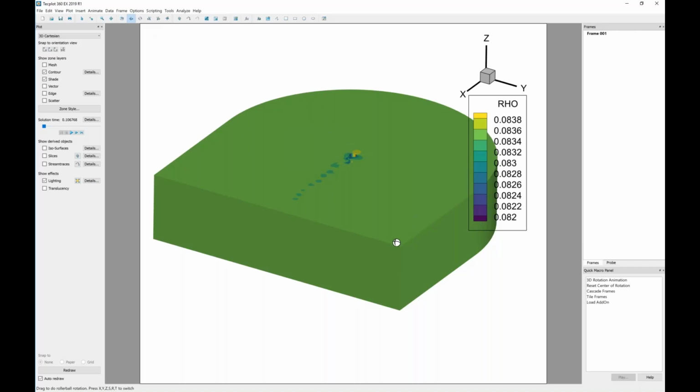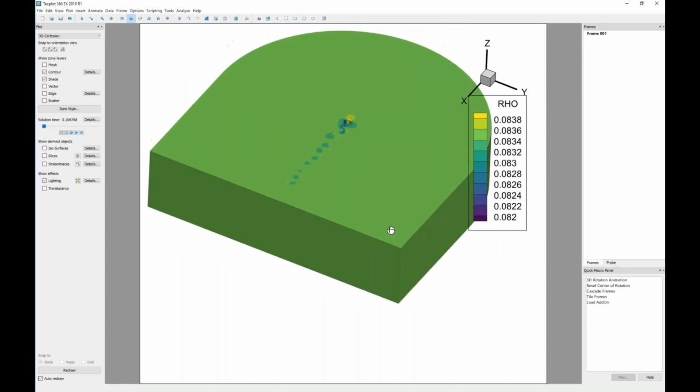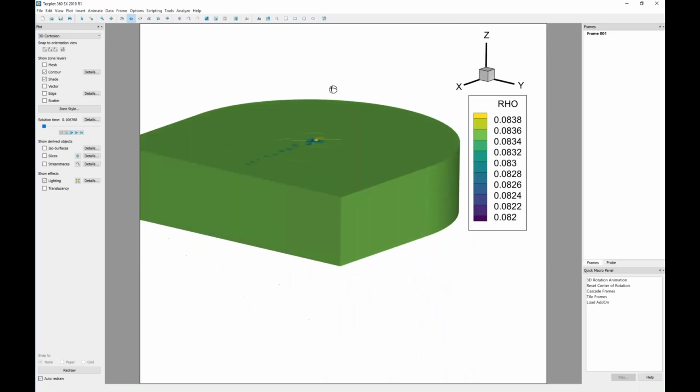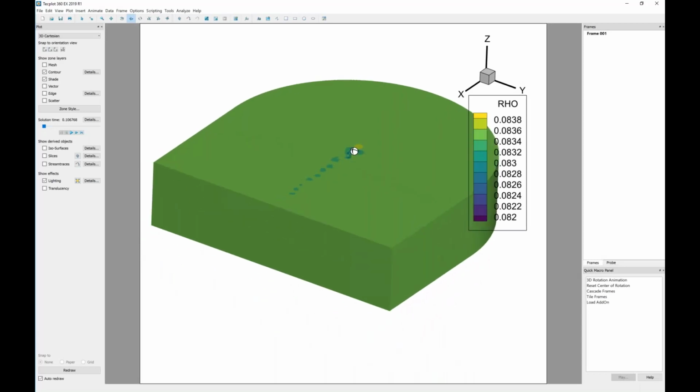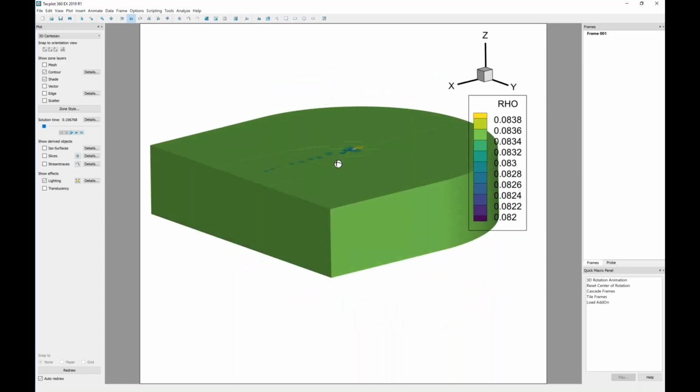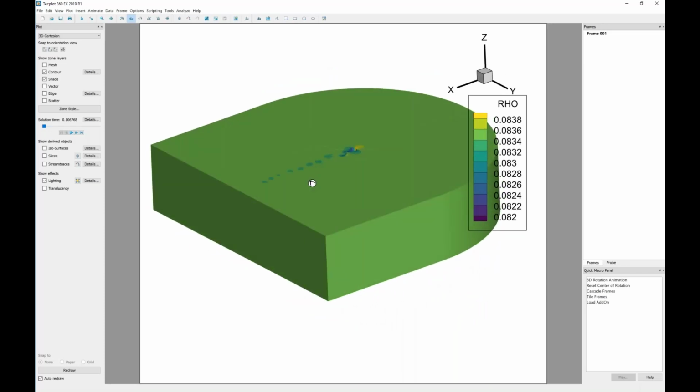Now, if you do have one of the rotate tools active, you can just press the O key on the keyboard to define the center of rotation. So now I'm rotating around this corner near me. And if I want to rotate around this far area, just press the letter O on the keyboard. And now I'm rotating about that origin. And here, I probably want to be rotating somewhere around the center. So I'll just hit O here, and now I'm rotating around the center of that object. All right, so nice keyboard shortcut there.